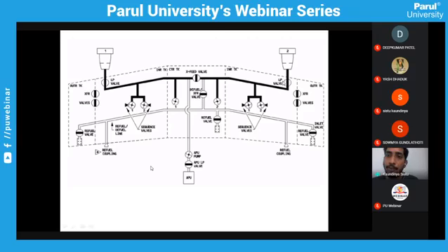If you close this valve, the fuel will not go into the engine, and here it will get stuck. Everywhere it will get stuck. Then you have to open this LP valve so that it can go into engine number 2. After getting into engine number 2, the engine gets started. Let's go to the left side now. Like this it goes, and this fuel will be off unless you are defueling or refueling. And this is the booster pump, so it's a dead end. So it will be going here.